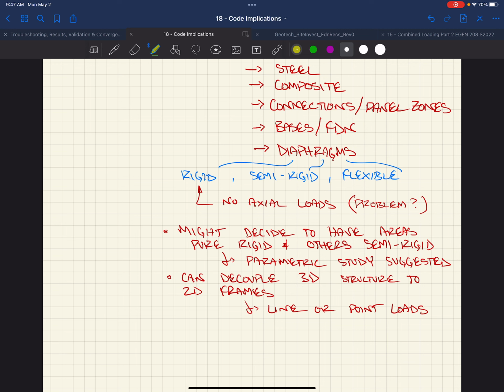VA, you used to be able to just pick a floor level, pick nodes, and click a box that said rigid diaphragm, and it just fixed all of those nodes relative to each other in that kind of geometry. Okay? They got rid of it because I think Adam agrees with me in saying if you're gonna model it, just model it, right? Make it semi-rigid.